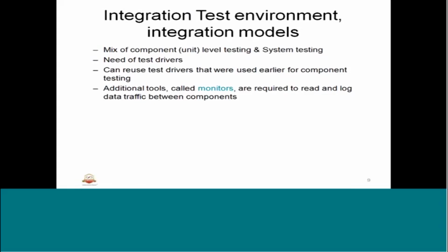So it's like an integration model which will be comprising of both unit level as well as system level environment. Basically, we can use some of the test drivers as well, which have been working and which are useful for integration to logically test the different modules together. Additionally, we may need tools like monitors to log and read the data traffic. As I said in the protocol, there will be a logger, timestamp, and all that. To do that, we need to have appropriate additional tools such as monitors.